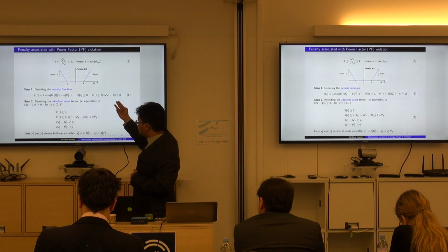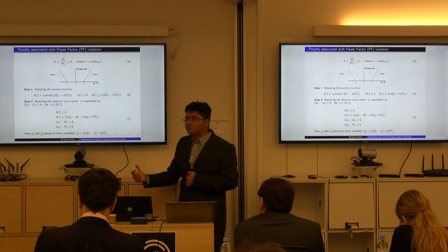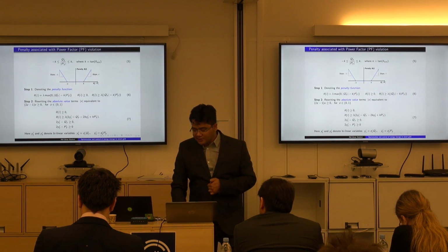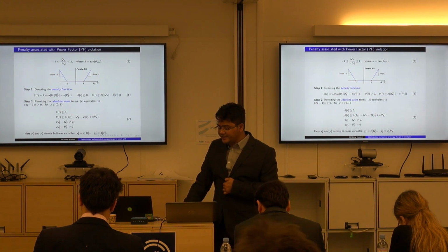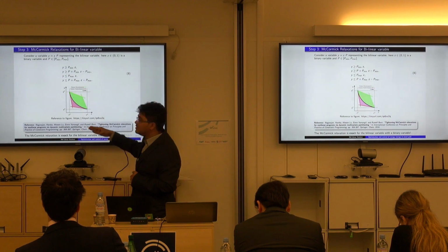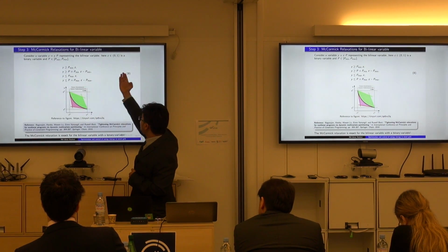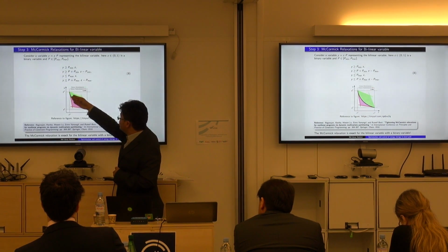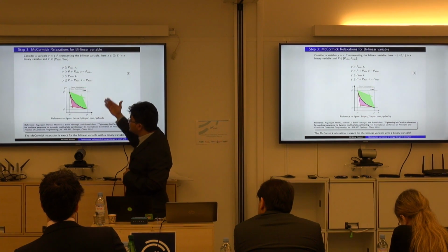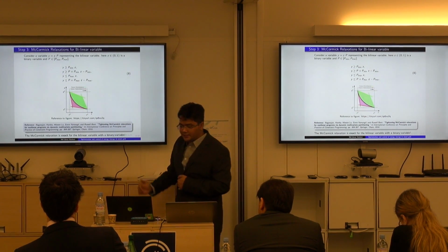Now, how do we deal with this absolute value? We can denote it with a binary variable, and when we extend, we find that we have two bilinear terms, which are the product of the binary term and the reactive component, and similarly for the active component. It turns out that we can use McCormick relaxation, which creates bounds on the space of the feasible region. Suppose y is the product of a binary variable z and p, where p has a lower and upper bound, and z already has well-defined bounds, 0 and 1. In that case the feasible region has this shape, and this approximation becomes exact when one of the variables is binary, as shown in earlier work.